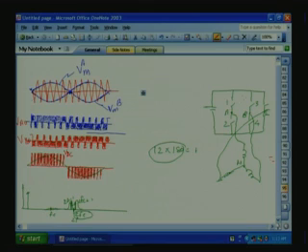So pole voltages will be switched with respect to sine-triangle PWM. When the sine is greater than the triangle, the top switch is on for the A phase; when the sine is less than the triangle, the bottom switch is on. For the B phase, it is the same triangle waveform, but the sine will be 120 degree phase shifted, somewhere here. That will be used for B. For the C phase, again another 120 degree, something like here. That will be used for the C phase. My sine waves are not correct, but you can draw it.